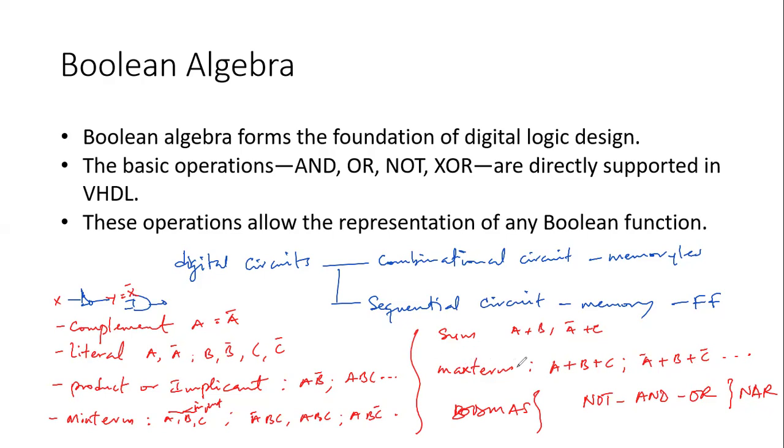Say, for instance, we have AB plus BC bar D. Let's place a bar here on B. It means that we have to perform the operation on B bar first, before we perform the product, then we have the addition. Then we have to perform the operation on C bar first before the AND operation. It goes in that order.